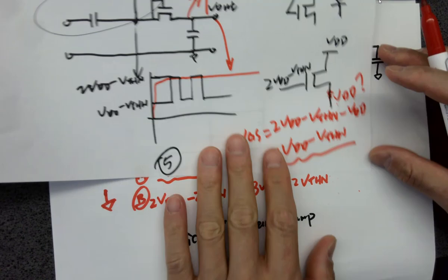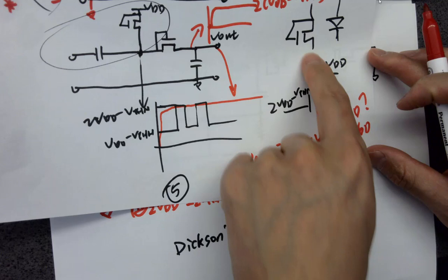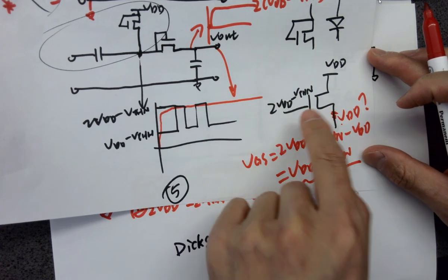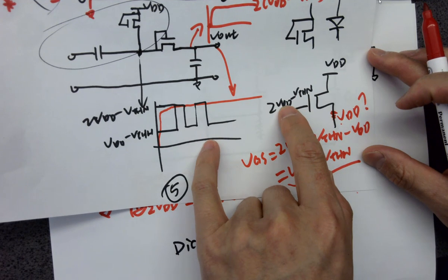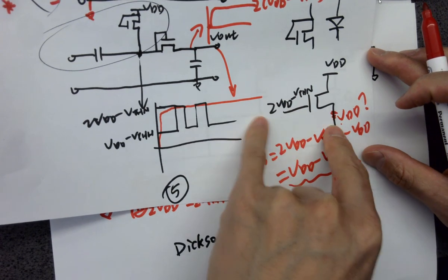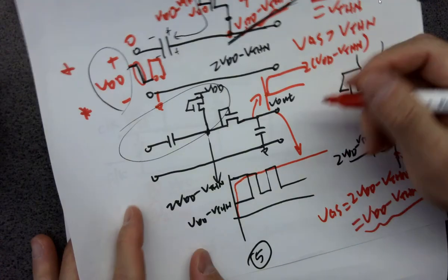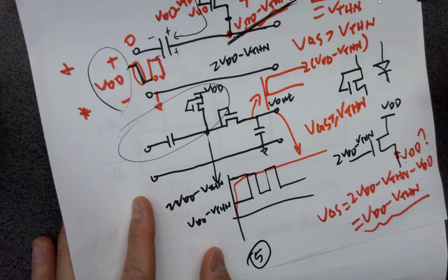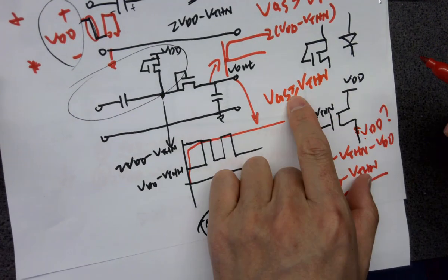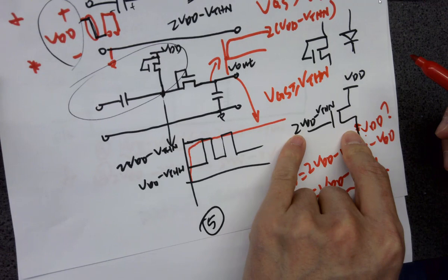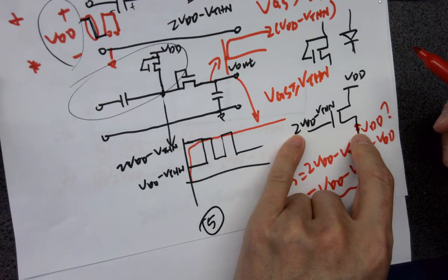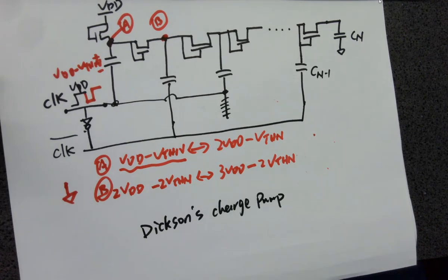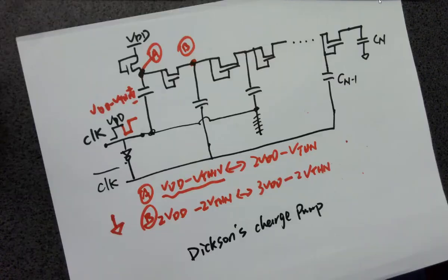But I have to understand why this happens, okay? Super important. I'm not losing the threshold voltage because I have a higher gate voltage. So I can form a higher VGS. And because you have to have VGS larger than VTHN to turn on the NMOS, now I don't have the problem anymore because this is always larger than VTHN, even though I'm getting a VDD at the source. Okay, for here,